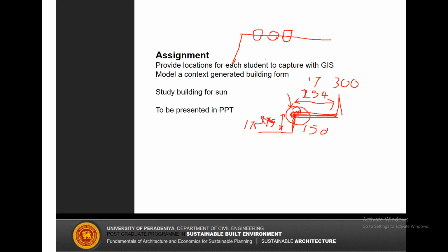So those strips are available to paste, but in factories in locations like Singapore, what I have seen is there are some stainless steel knobs like this. In section, it is kind of a nail kind of a thing. The surface is rough. So if this is a staircase, let's say this is the landing, you have to keep those knobs like this on the tip, so people will not slip. So not having this or an anti-slip strip is the issue, I suppose.